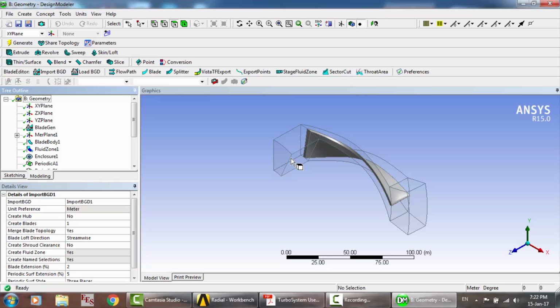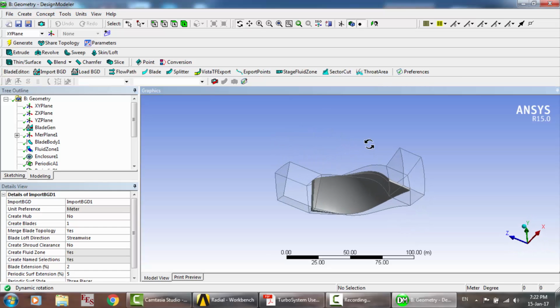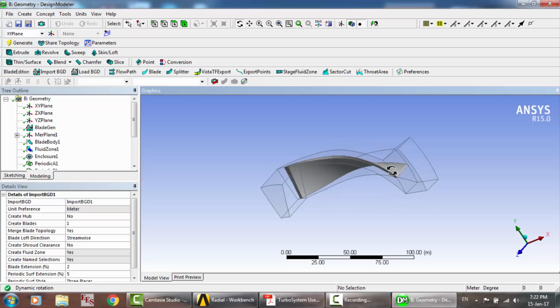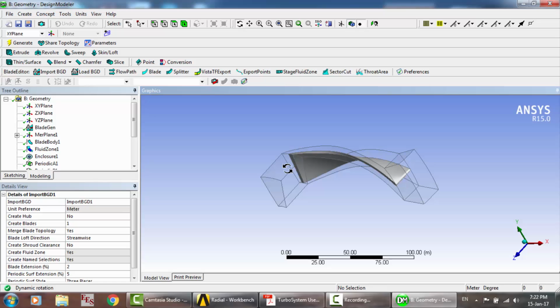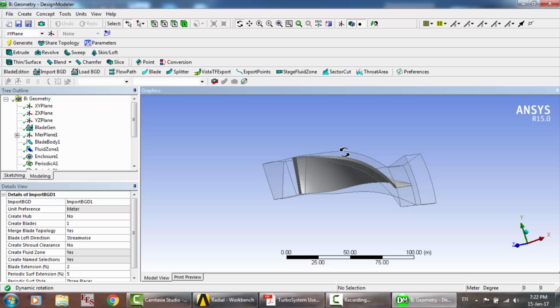As you know, if you want to use Fluent or CFX, especially CFX, if you want to use TurboGrid, you have to generate the flow path around the vane, because we are going to simulate or investigate the flow path, not the blades of the turbine, not the design that was carried out or generated by SolidWorks or CATIA or Inventor.